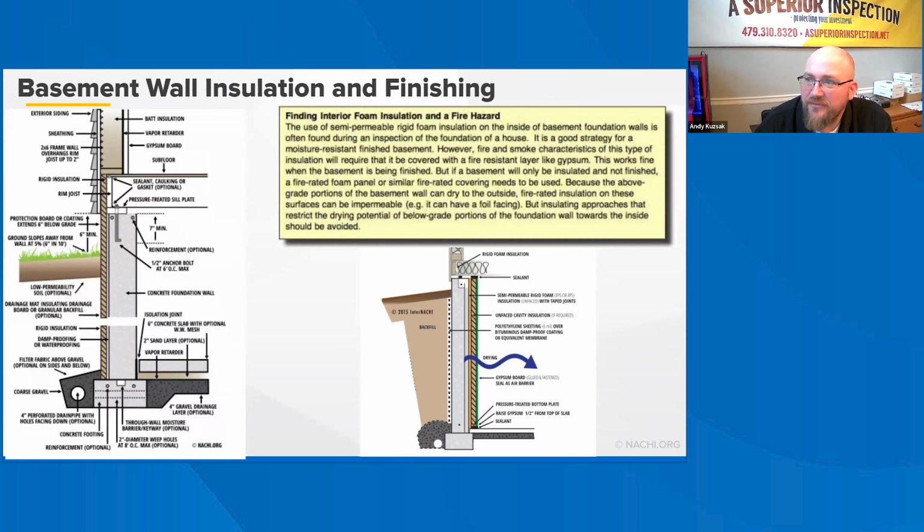The illustration shows a concrete foundation wall with exterior insulation using foam insulation panels on the outside for moisture resistance. The above grade wood frame wall, constructed of 2x6s, overhangs the foundation wall by up to 2 inches, allowing for additional rigid insulation over the entire wall assembly. This figure also depicts a sand layer beneath the floor slab. For interior insulation systems, the methods illustrated are becoming best practice in residential construction. This strategy is included here for those dealing with moisture problems under traditional practices. It is not meant to substitute for adequate waterproofing, drainage, humidity control, or air leakage control.